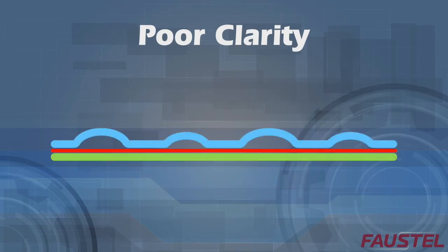A transparent laminate, unless designed for translucency, should have clarity and freedom from visible imperfections, at least to the degree of the individual components. However, this standard is difficult to achieve in practice. The most common degradation in laminate clarity is caused by incomplete contact across the adhesive and secondary web interface.